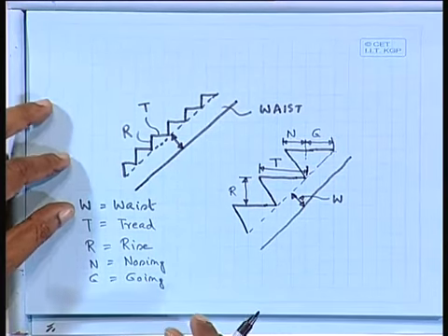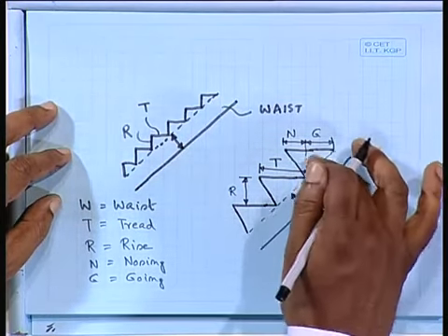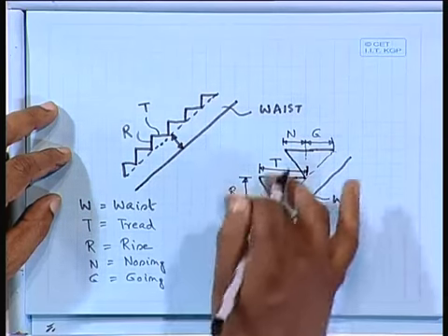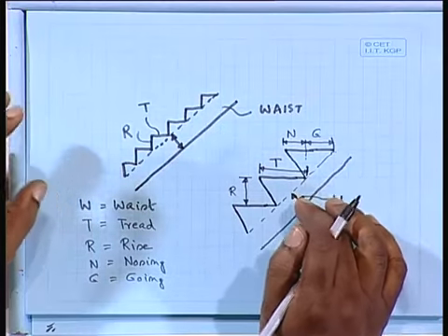So what we are assuming here, in this case, is that we shall take the dead load of these steps, but all the things will be supported by this waist slab. This is the most common one.